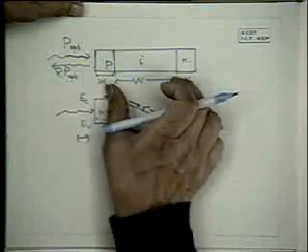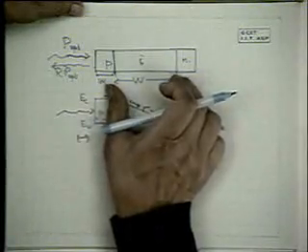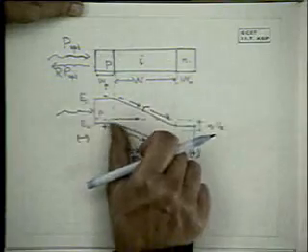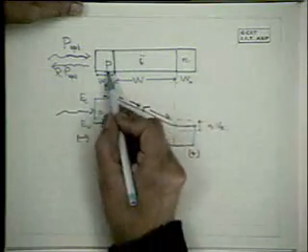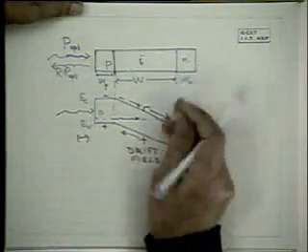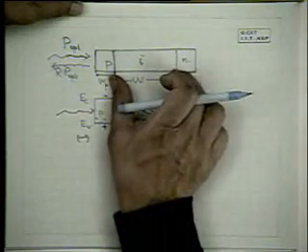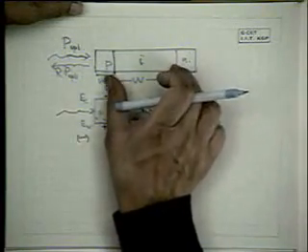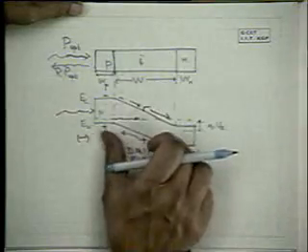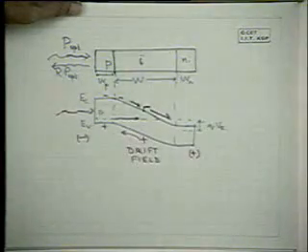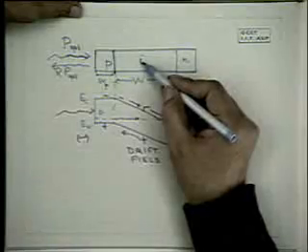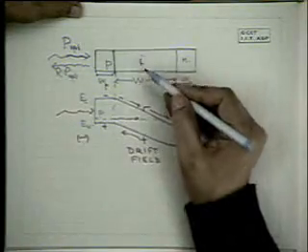Okay, so this sustains the electric field applied. If this is P and this is N, as you can see, this is a relatively high resistivity layer. So the voltage applied appears across this high resistive I layer. In silicon, for example, if you have a silicon p-i-n diode, you can make it an intrinsic device.